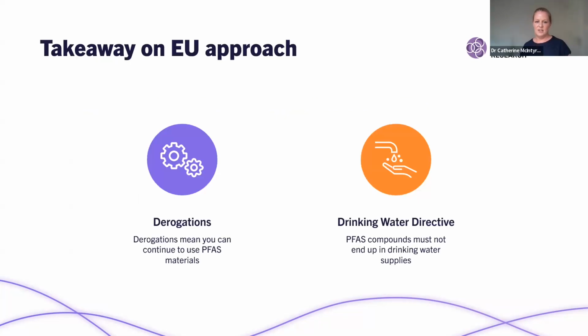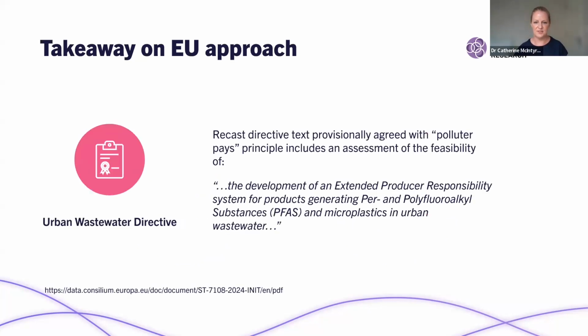So the takeaway on the EU approach: while they may aim to restrict the use of PFAS, the derogations, particularly for essential uses, mean you can continue to use those PFAS materials in your processes. However, bear the Drinking Water Directive in mind. PFAS compounds must not end up in drinking water supplies, so you need to be mindful of what's coming out in your wastewater.